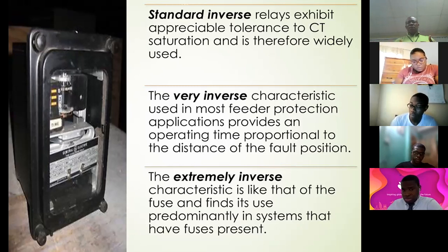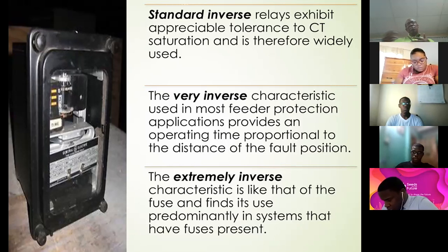Okay? So your very inverse characteristics provide for use on feeders. And with the extremely inverse, as I mentioned before, because their characteristics are so close, where you have systems that have fuses as part of that protection architecture, that's where you're going to find the use of your extremely inverse relays.